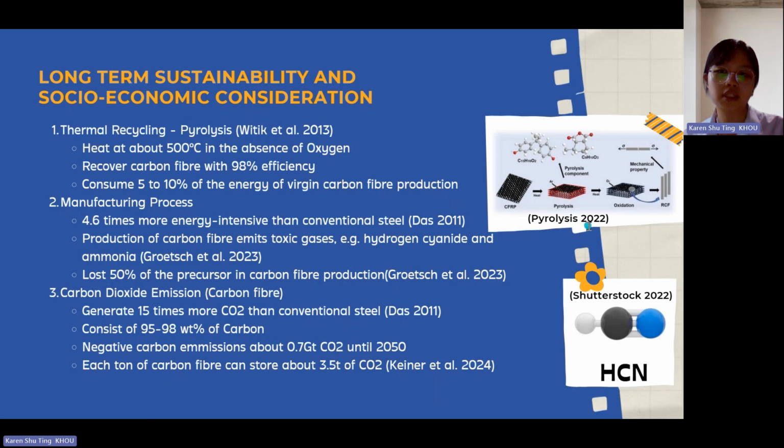It is a thermal recycling method that extracts carbon fiber from the carbon fiber reinforced polymer at an elevated temperature around 500 degrees Celsius in the absence of oxygen. It is able to recover carbon fiber with 98% of efficiency with comparable properties with virgin carbon fiber. It also consumes 5 to 10% of the energy of the virgin carbon fiber production.